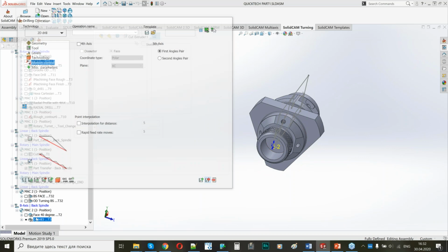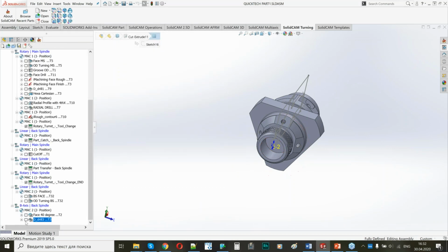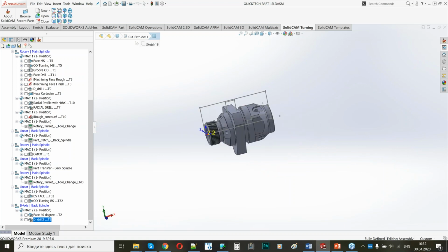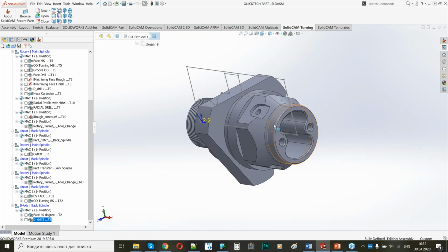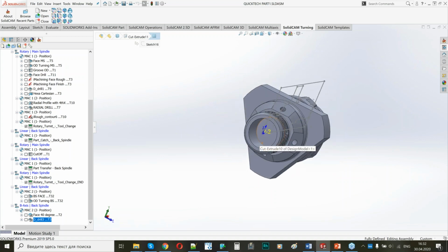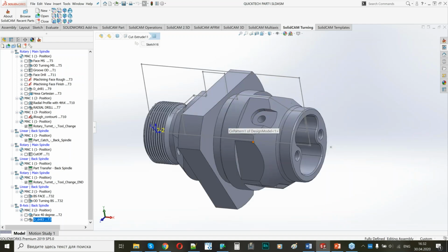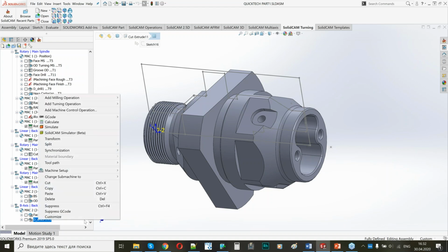Okay, of course I can add more operations here, but they will behave in the same manner as on a main spindle. I can also add some drilling and milling operations on the face, and threading operations, but we have one more project today, and I would like to go closer to the multi-channel machines and channel synchronization things. So here I would like the last operation.